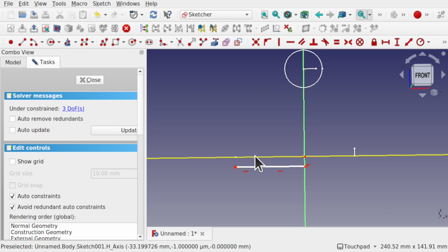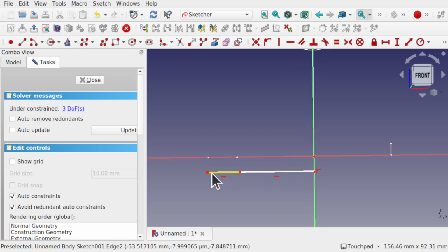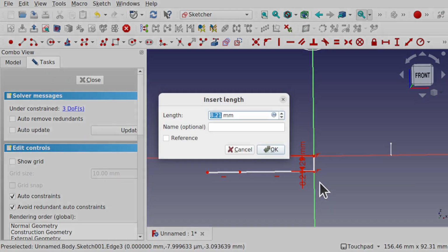Now attach my master sketch to this line. I'm just going to use underneath this line for this. I've placed that there because I want the center here. It doesn't matter, but we could have moved this up and done this. I've added that geometry there, and I'm going to add a length in here. So this one here. We've gone over constraints, so click the redundant constraint and hit delete, and start getting some lengths in here. I'm going to use the height first and click on this one.